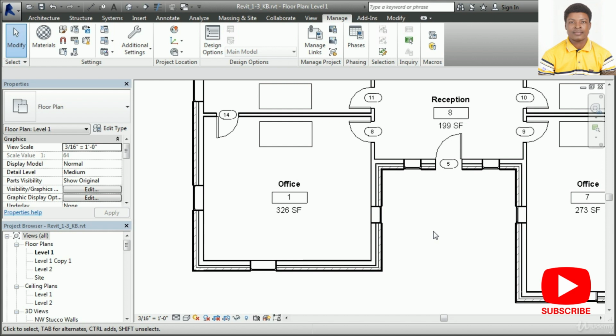There are two types of dimensions in Revit: temporary and permanent. Temporary dimensions appear as you are placing content or when an element is selected. Permanent dimensions are created by picking points or by converting a temporary dimension.